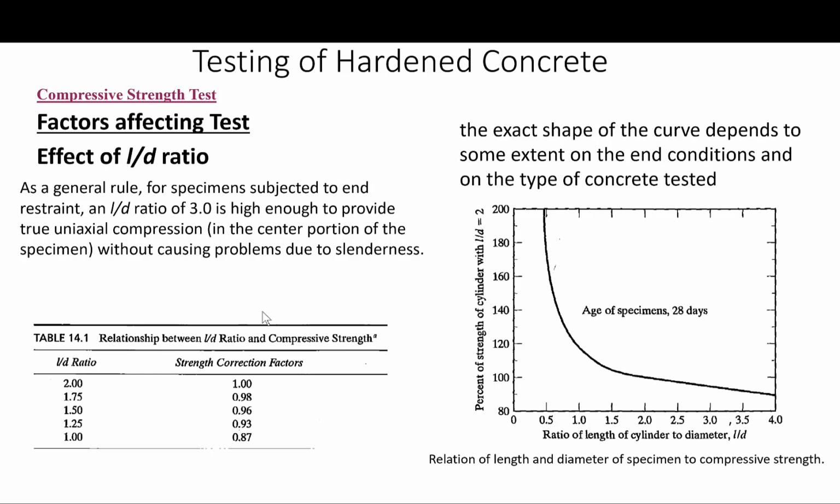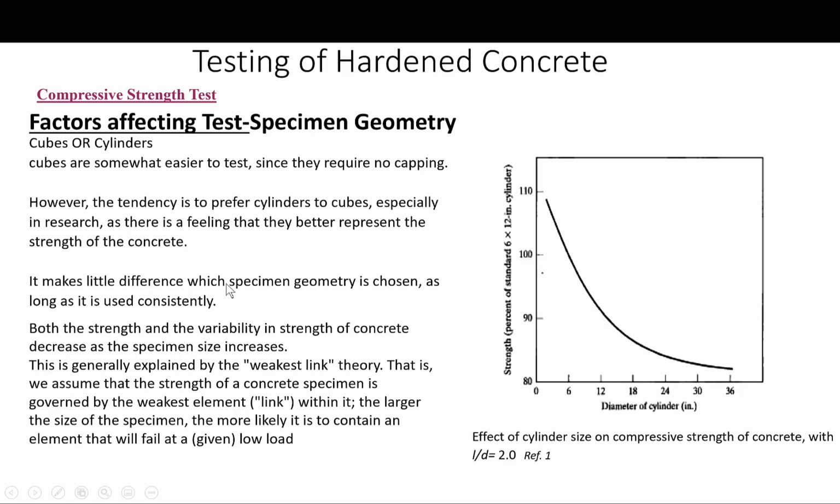If the L/D is greater than 2, the specimen can be cut to size before testing. So this is mostly, as I said, for drilled cores.